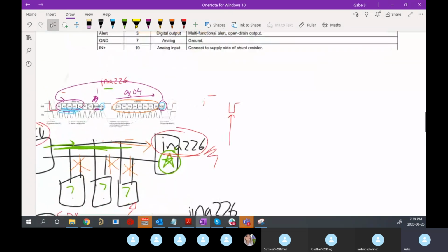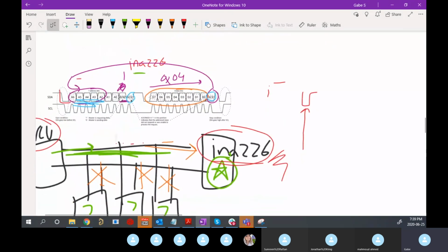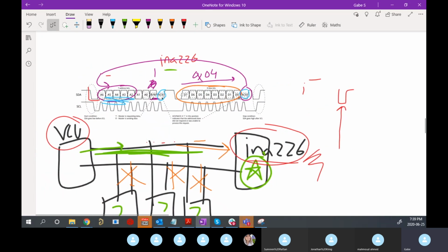But people really like it with small microcontrollers with limited pin count, and the fact that you can talk to a lot of things, just sending different addresses, and it's all built in. You don't have to write the software layer over top that includes an address in your data send, right? Like in UART, all you're sending is 8 bits, right? There's no address. So you could theoretically say, okay, 4 of my bits will be the address, and then the next 4 will be the data, and then you have to do all the software to actually handle that on both sides.